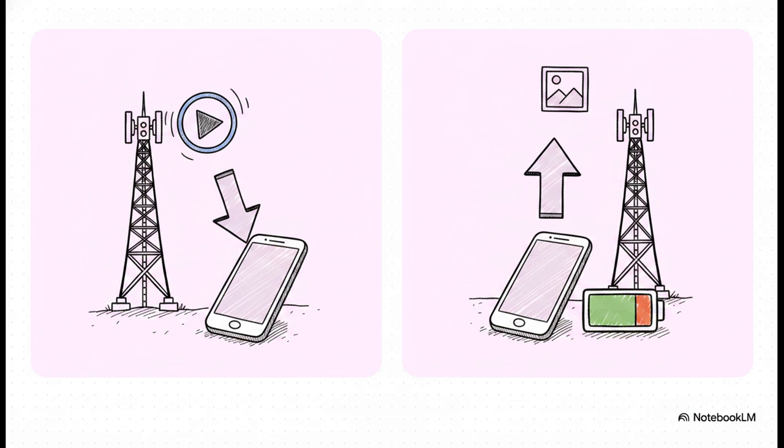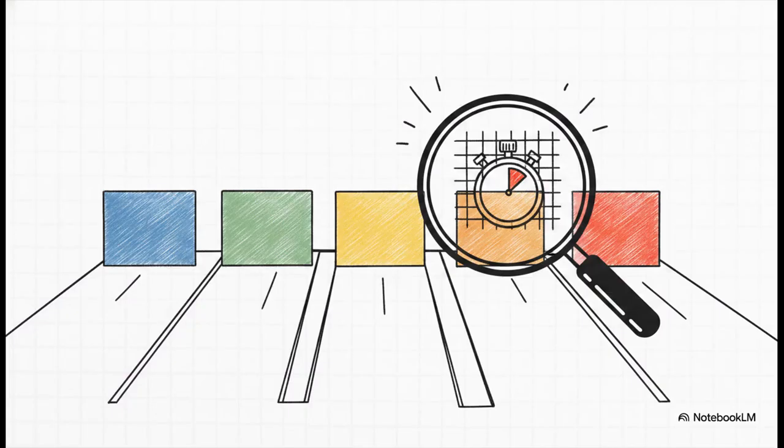Pretty smart, right? Now, if you think of network bandwidth as a massive highway, resource blocks, or RBs, are the lanes. According to the field notes, one resource block is made up of exactly 12 subcarriers, each 15 kilohertz wide, and they're transmitted over a tiny time domain of just 0.5 milliseconds containing 7 symbols. Okay, a lot of numbers there, but the golden rule to remember here? For every 1 megahertz of bandwidth, the network gives us exactly 5 of these resource block lanes.